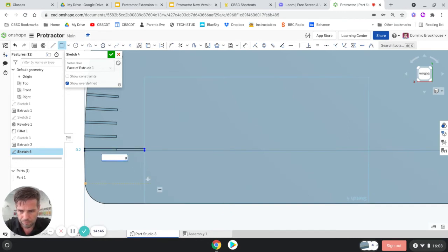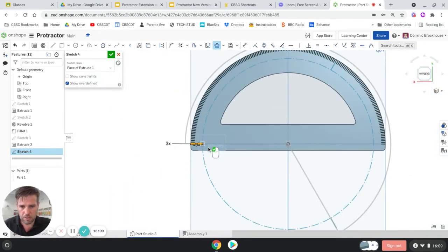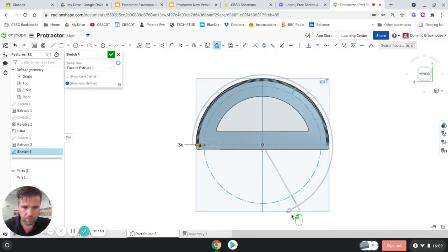And enter. And again, before we come out of this, we need to deselect our rectangle, drag a box around it so that we're ready to pattern that rectangle. Use the circular pattern tool. So the only variable that's different from the last time of doing it is that we've changed the length to 9 instead of 3. We're going to do the same on the pattern.